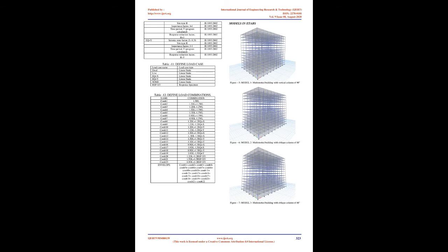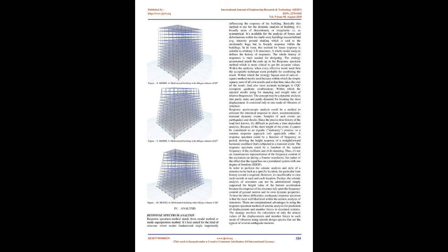2. Adoption of structural analysis program ETABS V18 in analysis and structural design models of RC high-rise buildings, and extraction of the design results for the types of structural systems with oblique columns, and calculation of the amounts of concrete and steel for the whole structure building and all models using an Excel program and making a comparison between the models.